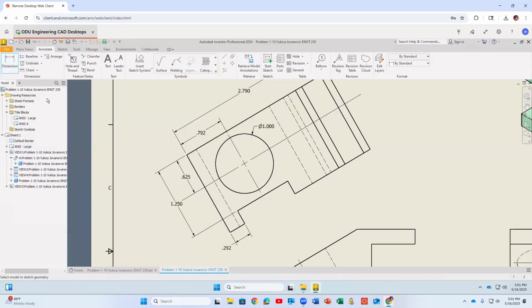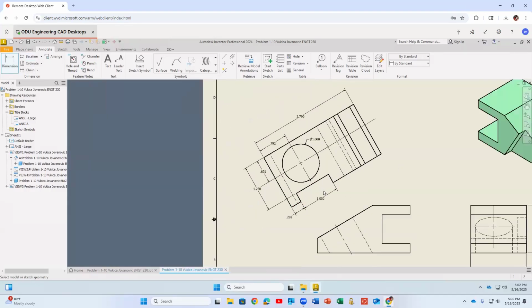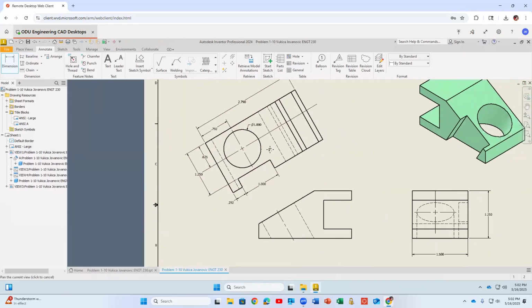And maybe I can just give a size like that, a rectangular shape. Okay, like that. So you see, in this way, I dimension where is this line with this. So I don't want to be dimensioning from two. I pick a line, and both of these locations are from that line. So I'm good with that one.